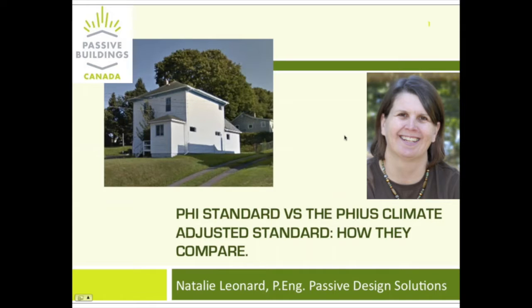Yeah, another good question. There's a mini calculator, and I believe this is in the resources page on PHIUS as well, that basically says that for a certain time of the year, you're definitely drawing heat out of the building and cooling the building, which you're having to replace with electric baseboard heat. So there's a calculator that downgrades the overall COP of the heat pump for the hot water based on what your climate data is, but also what your heating system is. So there's a little calculator to adjust that.